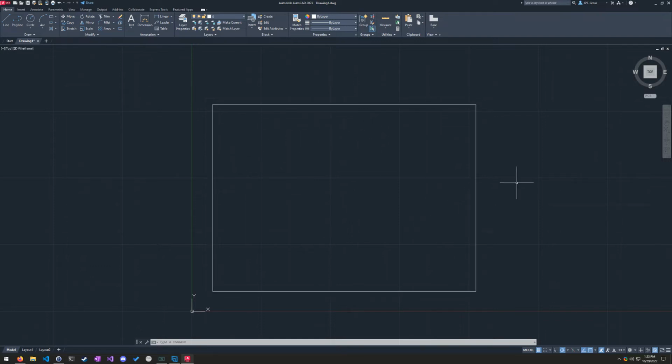So these are going to be lines. They're not going to be rectangles. So I'm going to use the line tool. That one's real simple. L. And notice that line is right at the top there, so I don't even have to type anything else, just L. Now I can press the enter key to enter into the line command. AutoCAD wants me to specify where the first point is. Well, the first point is going to be touching one of the midpoints of my rectangle.